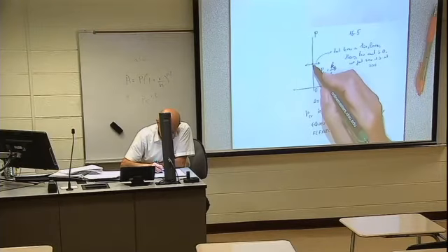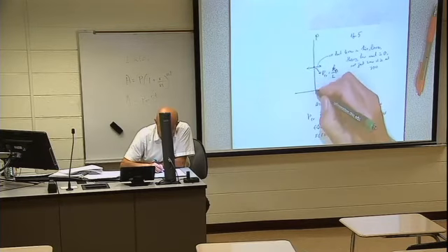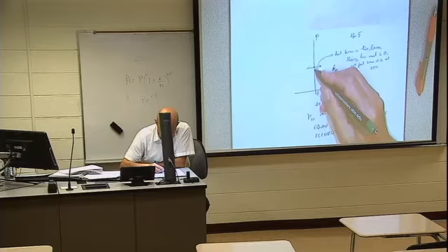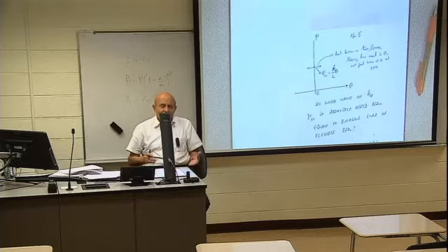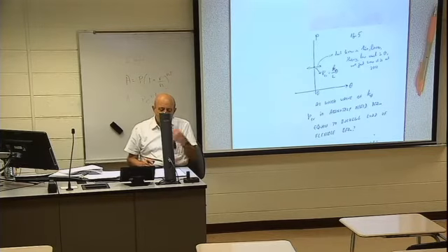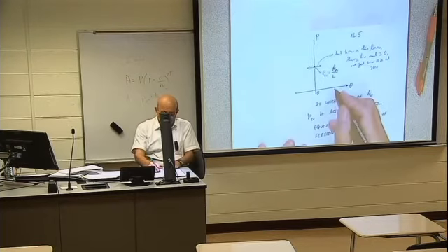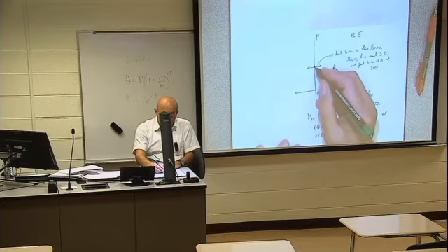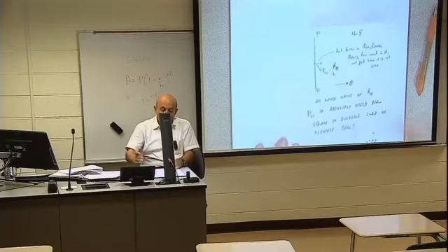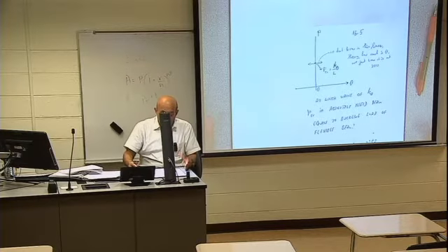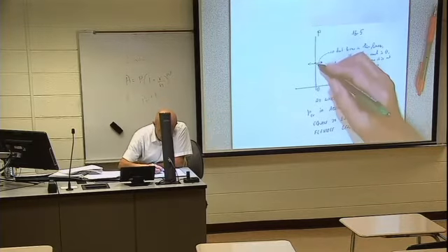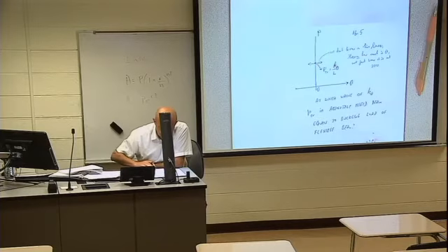Okay, so that is the situation. Everywhere this is 0, and for every P, displacement is 0. So, pay attention, that is a nonlinear behavior. There is load, but there is 0 displacement. But at some load, suddenly, the system wakes up from this deep sleep and buckles.